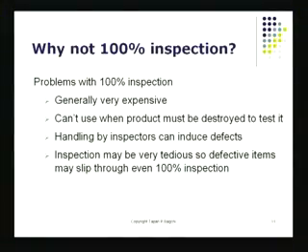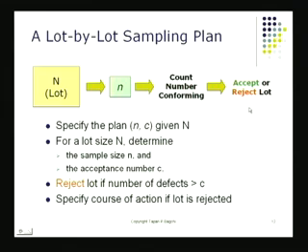That's also possible. And also it's a very tedious job. If I've got a couple of hours and all these different items and I must inspect all of them, my God, that's a pretty tedious job. So it's very possible I may go a little slack if I have to inspect a lot of items. If I'm going to be using the 100% inspection scheme, my job may become very tedious. I may get tired. I may make errors and so on and so forth. These are the different reasons why doing 100% inspection is not the way we should be doing our inspection.